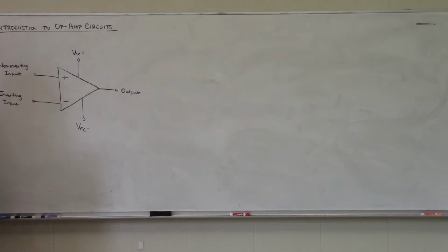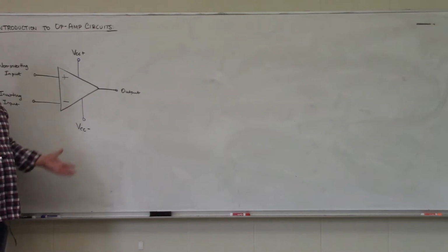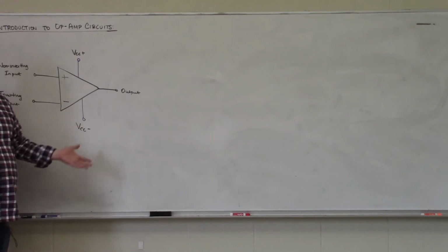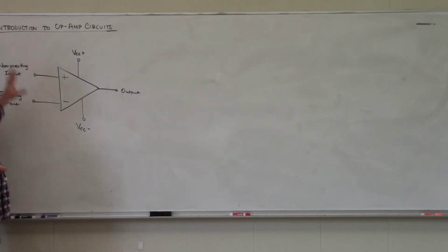The op amp is an example of an active circuit, so it requires external power to behave in a particular way. So resistors, capacitors, and inductors are all passive elements because they don't require external power to exhibit their specific resistance, capacitance, or inductance, but an op amp needs power to operate correctly. There's a lot of nuance in these power supply pins, as far as how the output voltages of the op amp can behave. But for the intents and purposes of Circuits 1, we are just going to assume that the biasing voltages are high enough to cause the op amp to behave normally.